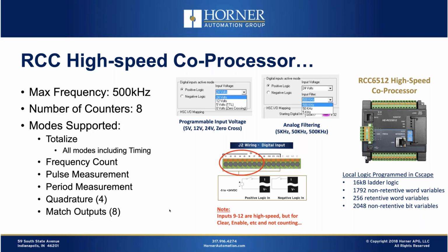Now, I don't have it on the screen here, but I will mention from an Ethernet standpoint, it supports Modbus TCP as a master or slave. It supports Ethernet IP as an I/O device. It also supports FTP file transfers. It also supports, I believe, email. So you could use this product to generate email alarms and those sorts of things. So it's still very functional, even though it doesn't have all the logic space as well as all the protocol support of every OCS.